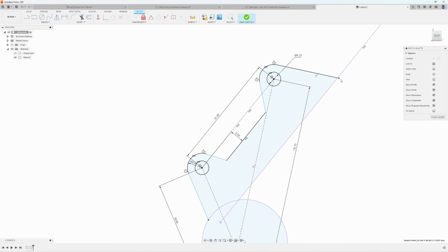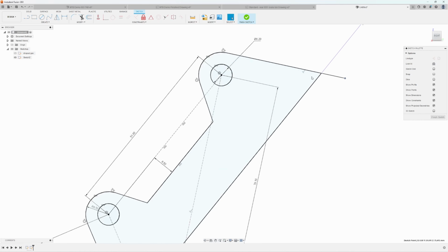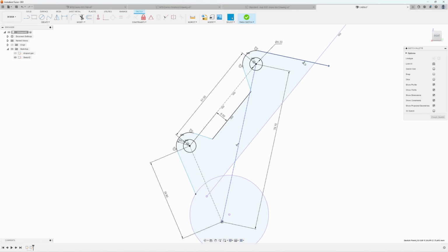And you see how this happens a lot, and you need to know how to fix this in your sketches. But I want to be able to move this line up and down, just like I can change this angle. But for some reason, it's locked in place. And you can see here, it has this perpendicular constraint, which I don't even know what is. For some reason, when I drew the line, I wasn't too careful, and I made it snap to perpendicular between this line and this line, which is not what I want. So if I select this constraint and I delete it, now you can see this line is free to move again, and I can position it where I want.